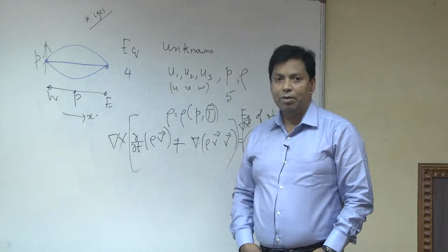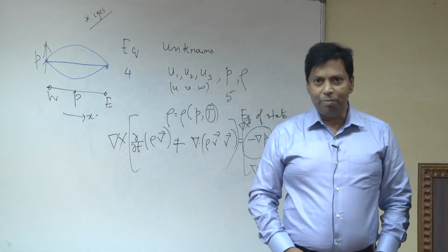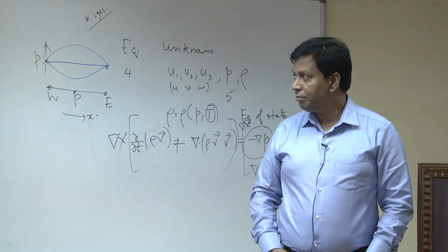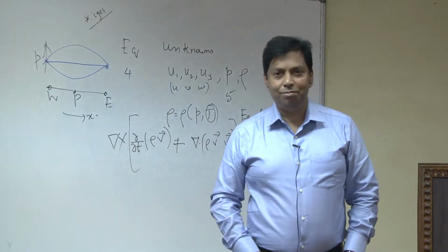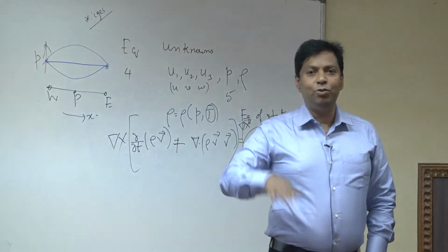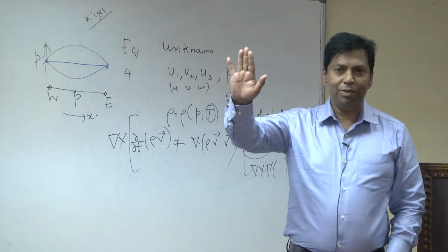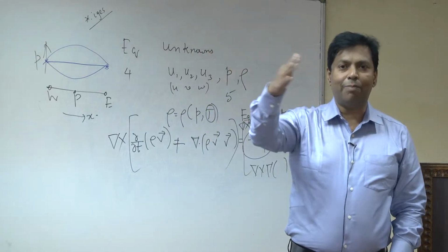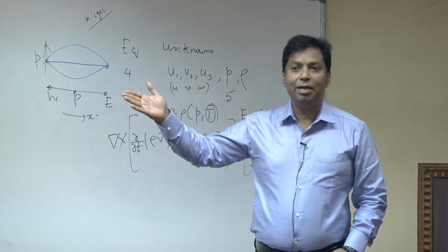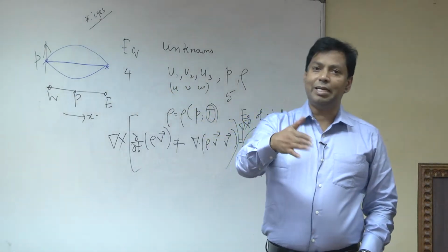If you have a complex kind of problem, you have to work on it, especially since Fluent is given the main scheme. Generally when we use our own coding, we do not touch the main scheme. We touch some other subroutine where you need to change. For this kind of thing we have to write a user defined function, meaning it is another subroutine we have to attach to it.